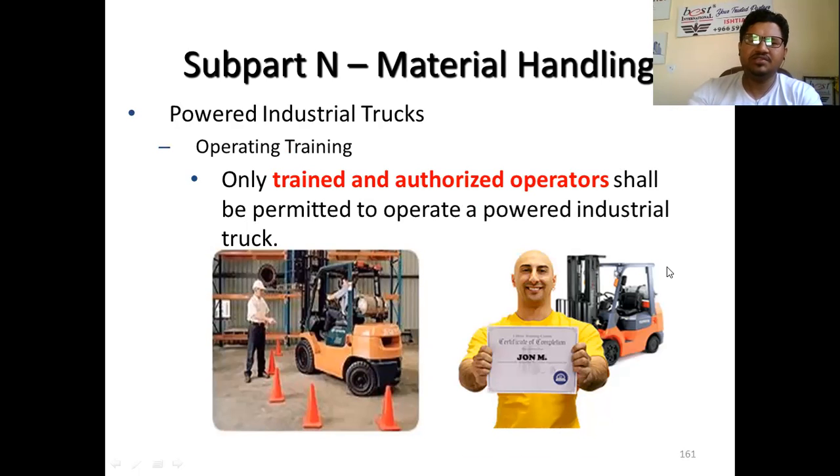Make sure there are properly trained and authorized operators. I mean, even if you are a supervisor, but you are not an authorized forklift operator, you're not trained, you don't have any certification, you're not authorized to operate a forklift. Even if you know how to operate it, you're still not authorized because you don't have any evidence or ID that you are a trained forklift operator.